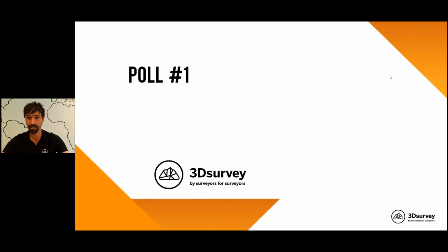Most of you already answered, and we see 28% yes, 60% no, and 13% of you selected what is LiDAR. Just a quick explanation: LiDAR is actually a laser scanner which produces point clouds similar to photogrammetry, but by default it does not have color. You can put LiDAR on an aircraft, even on a drone, and map the entire area with it. The same project we did today with photogrammetry, you could also do with LiDAR, but of course the equipment costs 10 times more and so on.